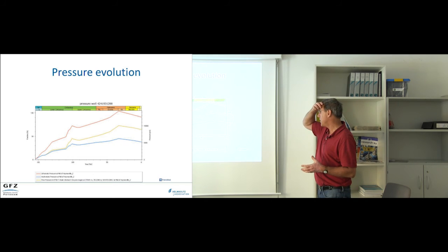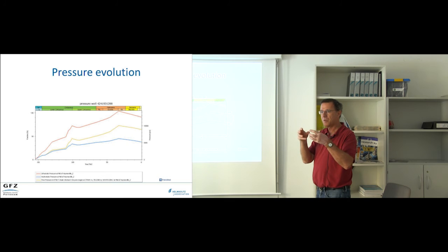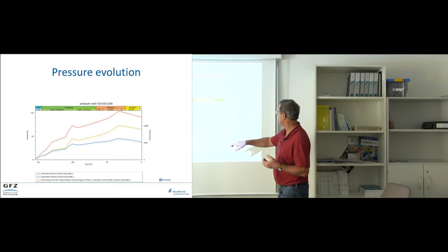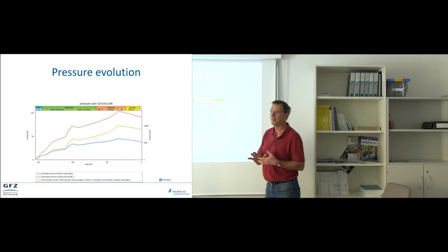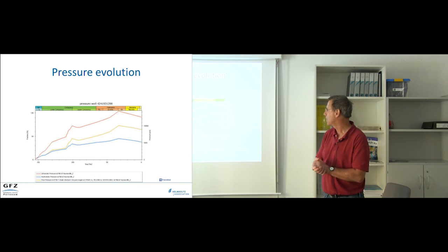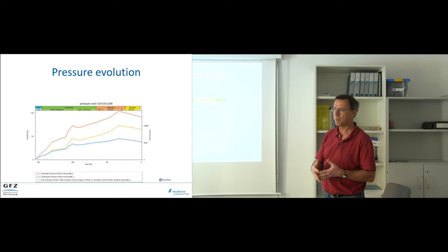In this curve, it is really just the amount of water which is not released, which then starts to carry a certain amount of the additional load due to sedimentation. Assuming this model, we get about 50% of the overpressure which is measured in several of the wells. So we started to look for additional mechanisms which could increase overpressure in this area.